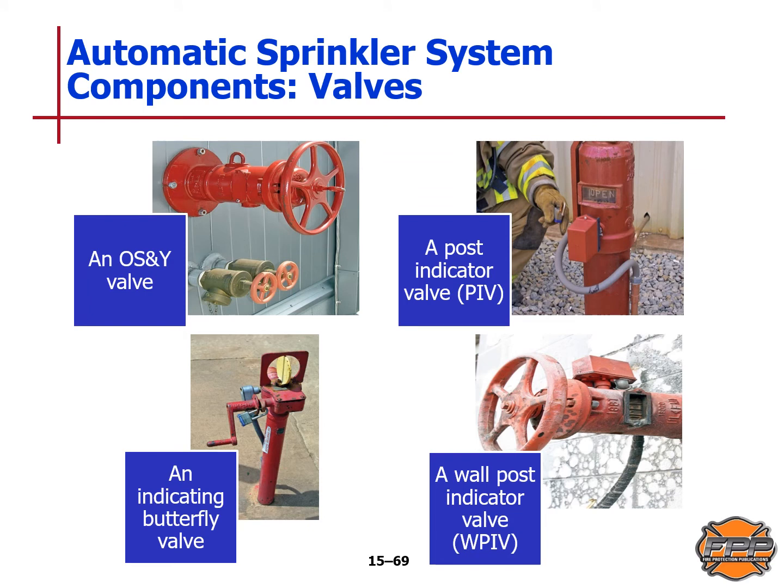These are examples of each of these. On the left you see an OS and Y valve. On the right you see a post indicator valve. The bottom left is an indicating butterfly valve. And on the bottom right you see a wall post indicator valve.